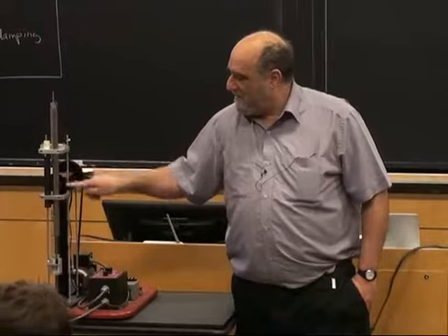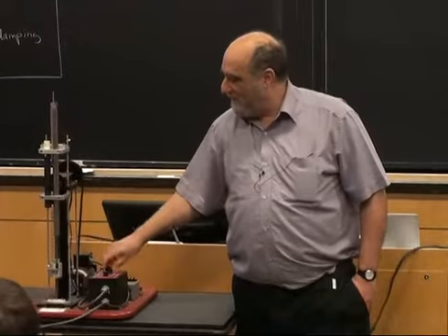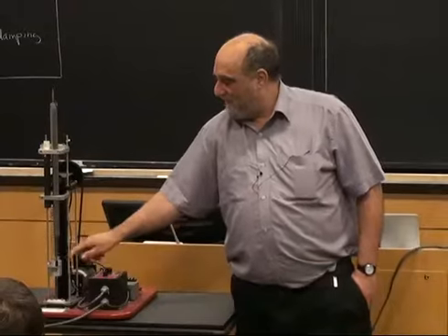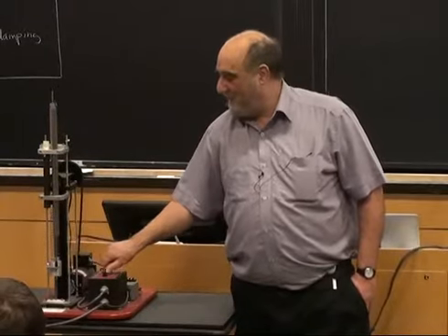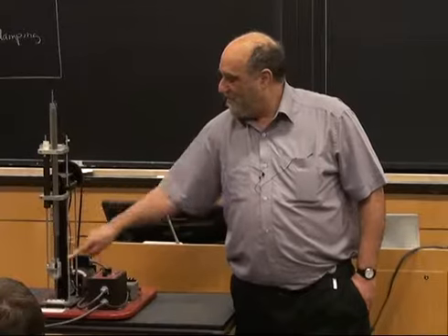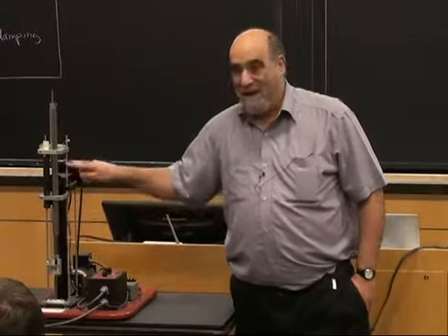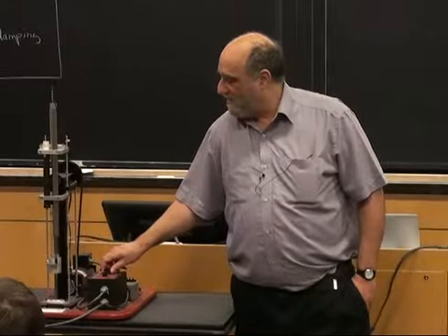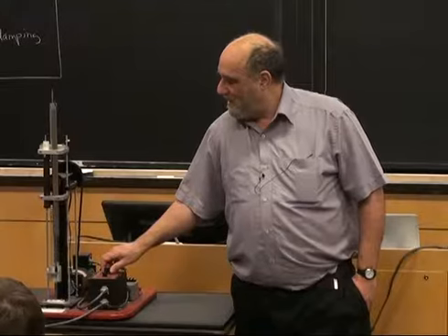This displacement is fixed in amplitude but variable in frequency, and what we can see is what the response is. At high frequency, this goes up and down a little bit. At very low frequency, it goes up and down. The bottom just goes up and down following the top. And at some in-between frequencies, I can get pretty big amplitude motion if I get it right at the so-called resonance.